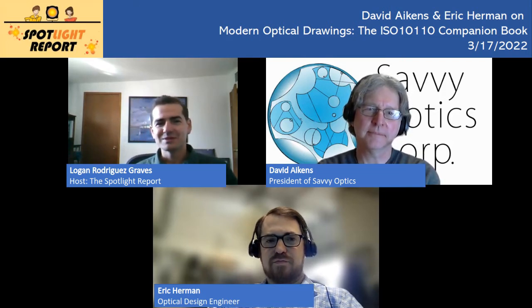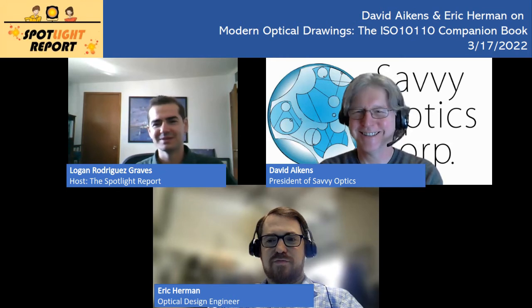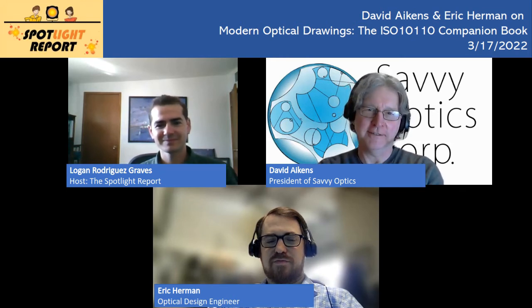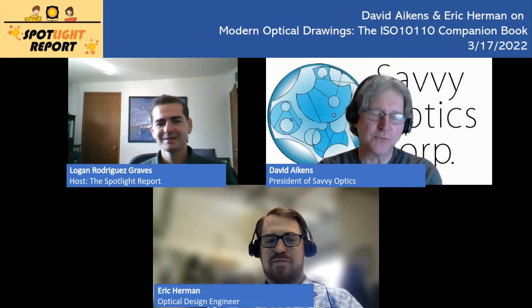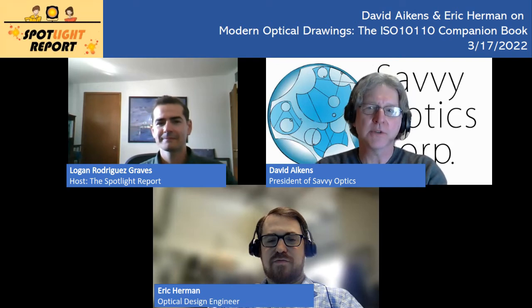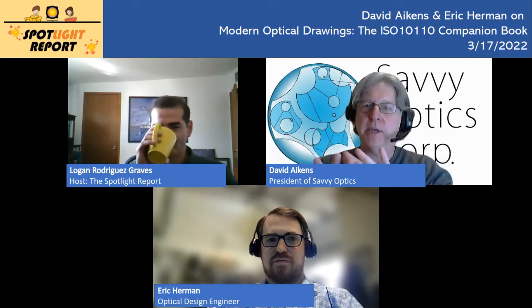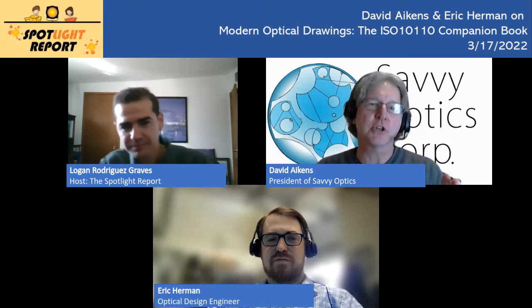What is the difference between surface figure and form and surface texture? I don't get it. Why would there be any difference between these things? It's all a matter of scale. The surface form is the shape of the surface on a large scale, and we think of form errors as covering the entire part. So maybe a little bit of changing curvature.